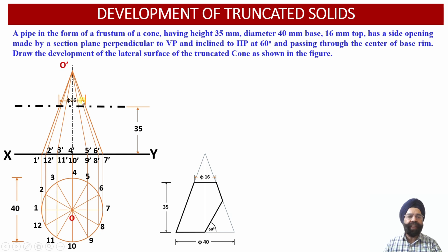It is going to measure 16 millimeter circular projection over here. So if we are going to look at this frustum top face from the top, once we draw two perpendicular projectors into the top view projection over here, we are going to obtain the circular projections corresponding to the top face of the frustum of the cone in the plan projection view.